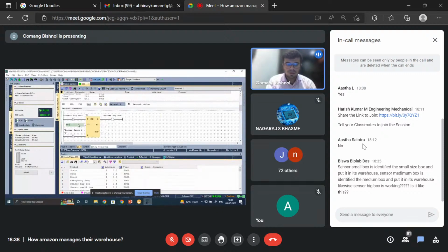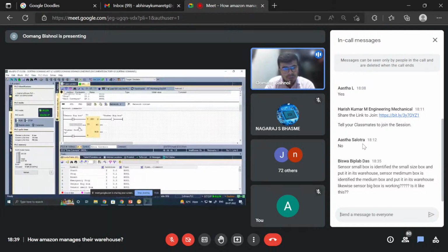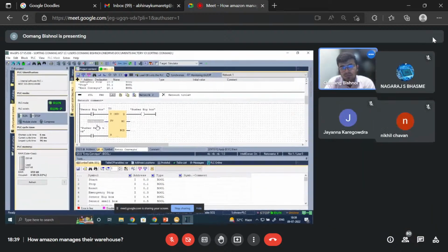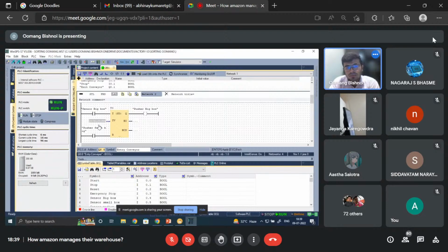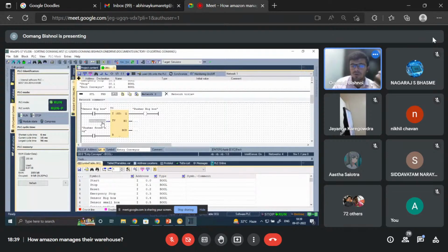S5T#1S. Now, what do you think? Why do you think I have given this 50 ms here? What do you define by this 50 ms? It is milliseconds. Yes, actually. So 2 seconds would be too much for it, and 50 milliseconds might not be enough. But it is hit and trial.